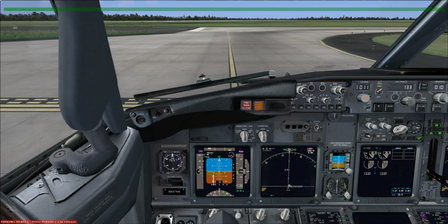If a microburst occurs to your left or your right during takeoff, then that also has its challenges. If it occurs while you've just started the takeoff roll, while your indicated airspeed is still very low, let's say too low for the rudder to have any effect, then the wind would push the vertical stabilizer one way and swing the nose of the aircraft the other way, and you might go off the edge of the runway without any control, and nose wheel steering wouldn't be able to help you.